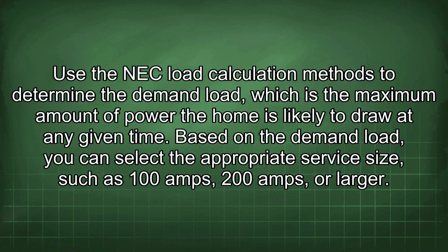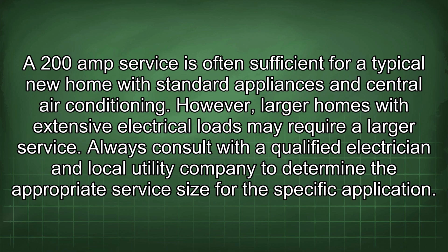Based on the demand load, you can select the appropriate service size, such as 100 amps, 200 amps, or larger. A 200 amp service is often sufficient for a typical new home with standard appliances and central air conditioning. However, larger homes with extensive electrical loads may require a larger service. Always consult with a qualified electrician and local utility company to determine the appropriate service size for the specific application.